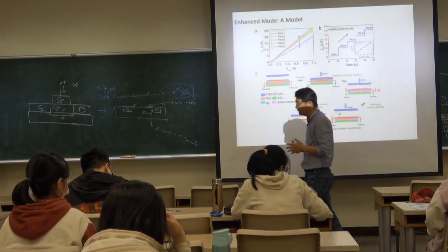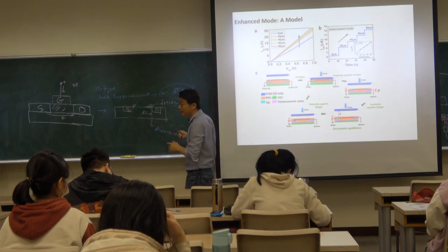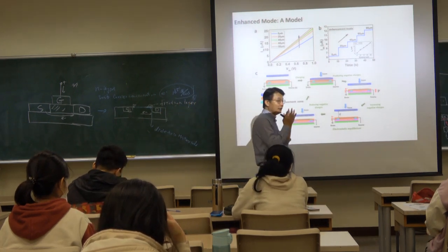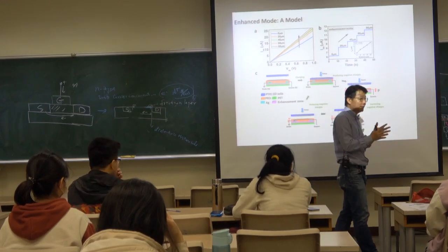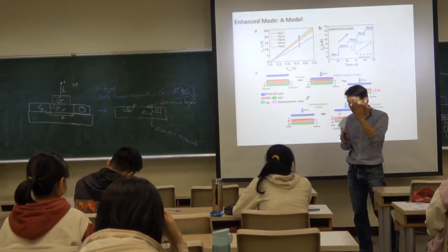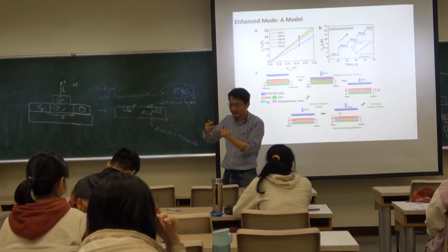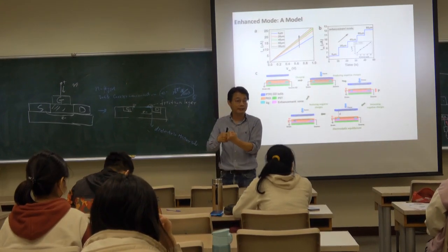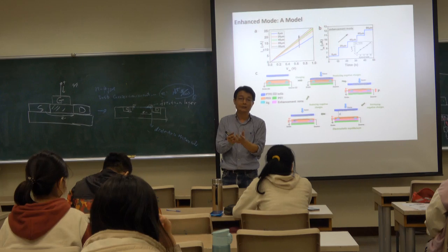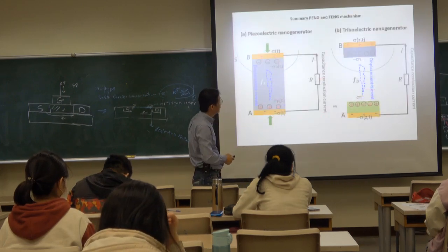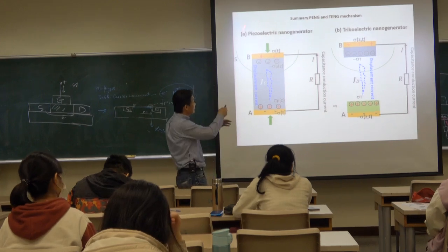Okay, so we use the two separation modes to easily demonstrate that this is possible to use in a FET device. We call it tribotronics. So-called if the material simultaneously has two effects, one is the triboelectric effect, another one is the semiconductor effect, you should be able to make a coupled device. So this is just a summary.